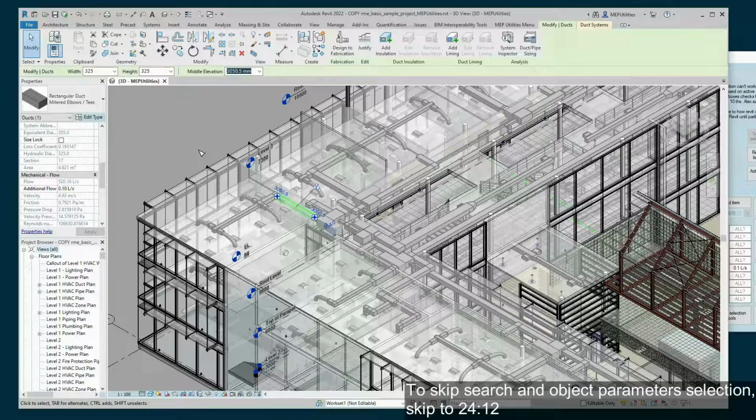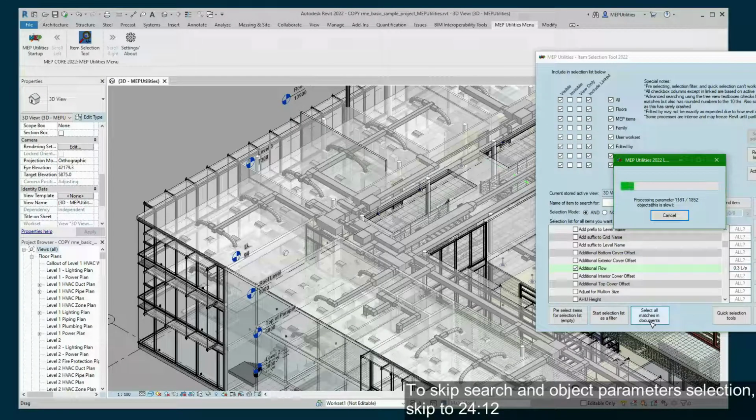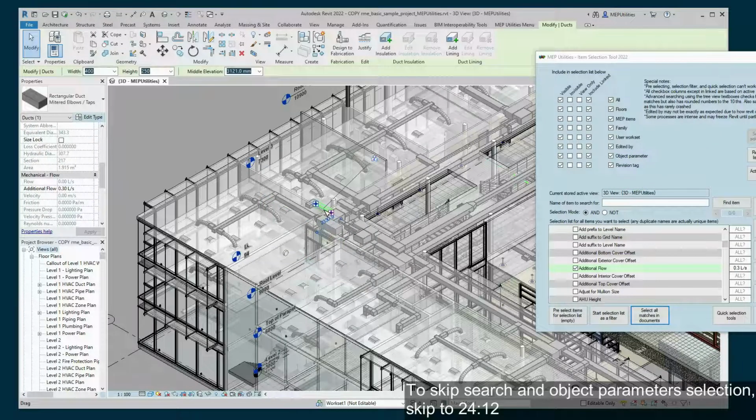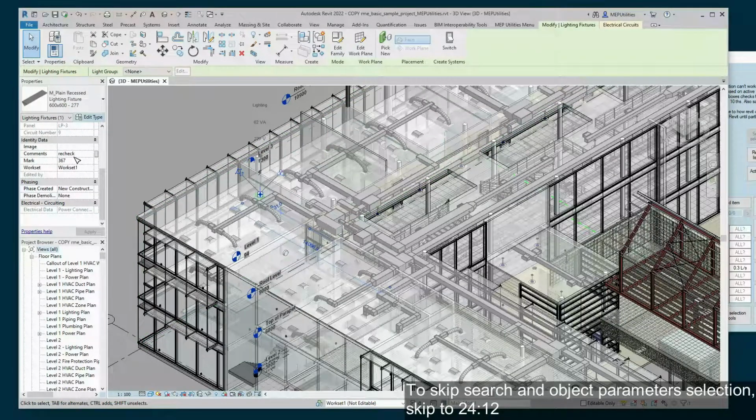So that just made it really easy for me to find specific flow rates in an entire building that were subsets of duct that I wouldn't necessarily know right away. In fact, let's look for the other example I have. There was one that I had at 3. There you go. That one is 3. So that didn't take any effort, and I can export a list of the IDs if I ever want to come back and check on those specific parts or find them in the program at any other point in the future. So that's really powerful, and it can also be used for other situations like comments here.